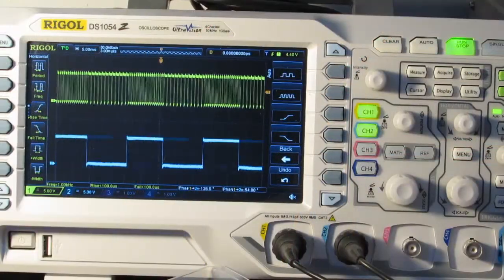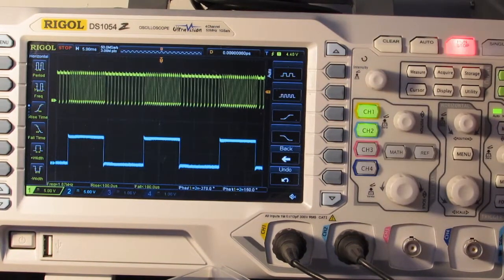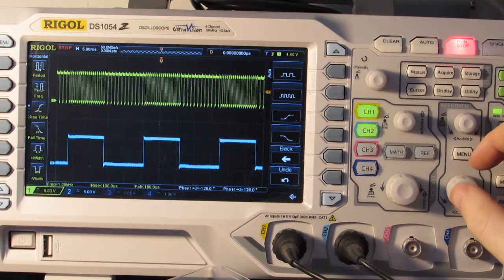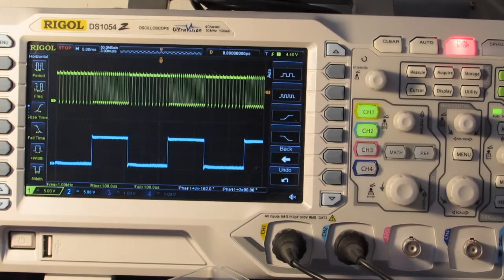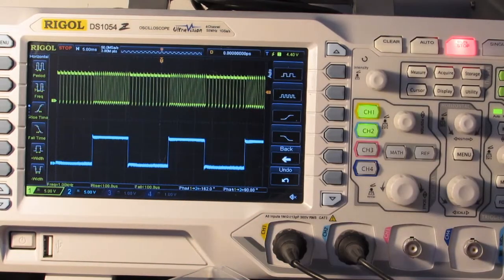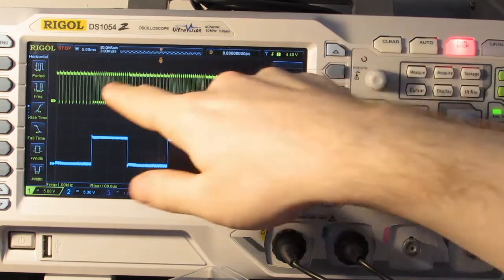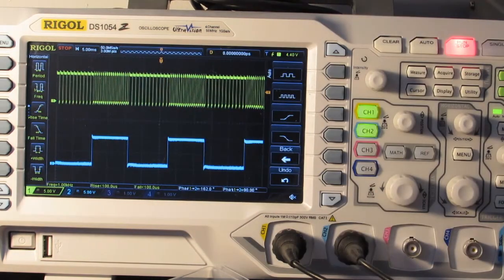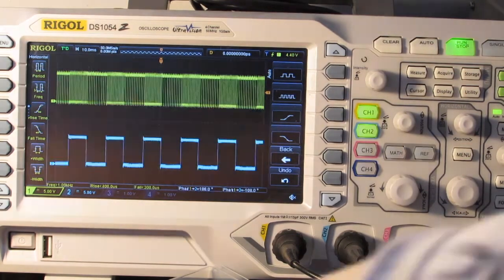Right, okay, so here we are on the oscilloscope and we're looking at the 2 oscillators. Now let me just pause this. Ooh, nice. It's quite a good example. So here we can see the blue trace on the oscillator is our first oscillator, right? And this is the one controlling the pitch. So essentially we've got 2 oscillators running. This is our pitch oscillator, which is going to dictate our perceived pitch, and this is the kind of sync oscillator which is going to run alongside this oscillator and give us that sync effect. I'll let you see how that sounds.